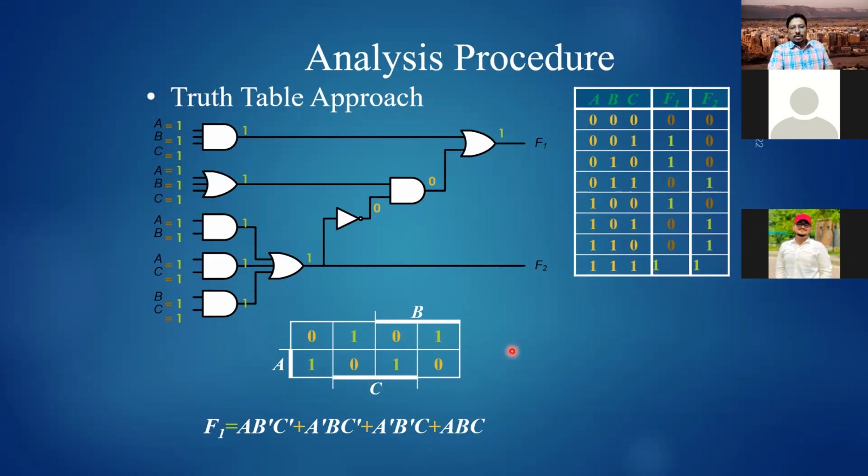Okay, so if you have only this small K-map here, you can build your circuit. It gives you the same results. You can consider it a verification of the results you got from the simplification of F2 in the previous one, which we did. Now here you can see this is A, B prime, C prime.